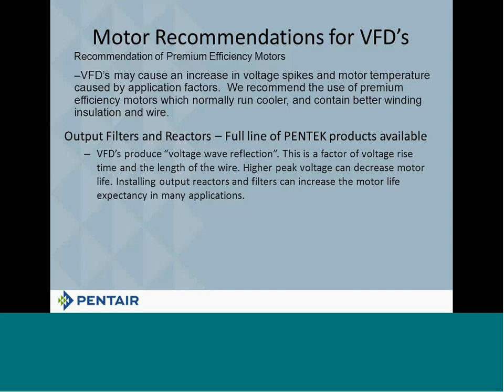You can raise the pressure by 10 times by slamming a valve shut. Similarly, when we're talking electricity, what happens is when that sine wave hits, if it hits at just the right point, we can raise that sine wave above what the voltage of the motor can handle. And that's what's going to get delivered to it. So we're going to talk a little bit here about filters and reactors, because filters and reactors can help bring that sine wave down and eliminate some of that hit.